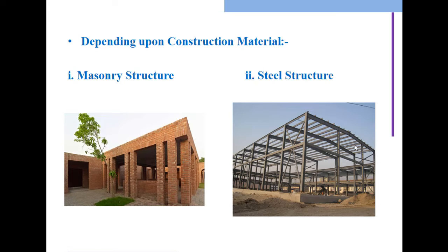In ETABS you can see this kind of structure very easily. Even in STAAD Pro, these things can be very easily identified and designed. But for that you need an extension of an Excel sheet to design, because this software only gives you the shear force and bending moment values. The rest of the design you need to perform.